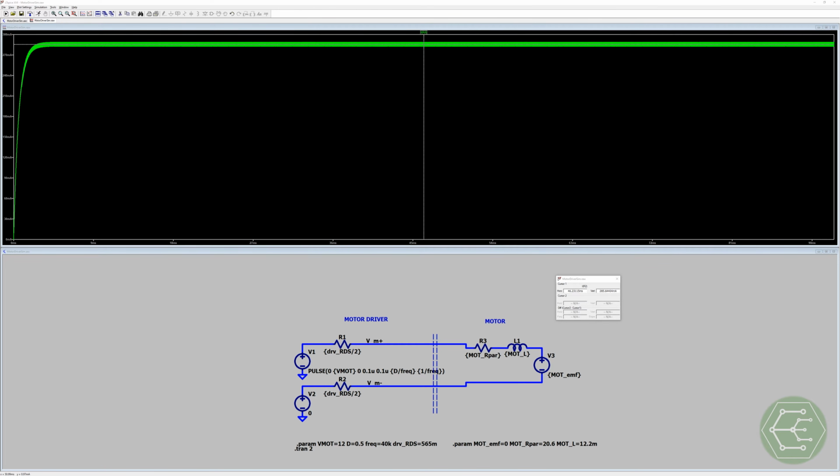0.08 amps, which, according to our model, would lead to a voltage across the motor of only 1.6 volts, which would mean that our back EMF was 10.35 volts. Now, I don't know if that's realistic. I could have just forgotten a number or written it down wrong. I don't actually have the appropriate characteristics of this motor to know for sure if that's right or wrong.